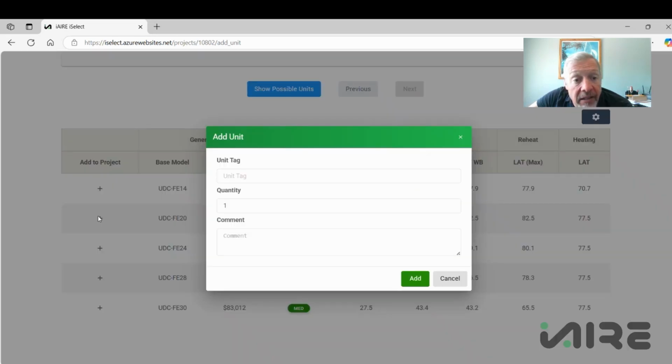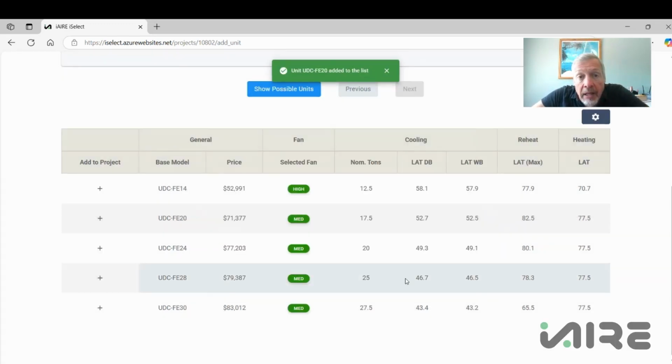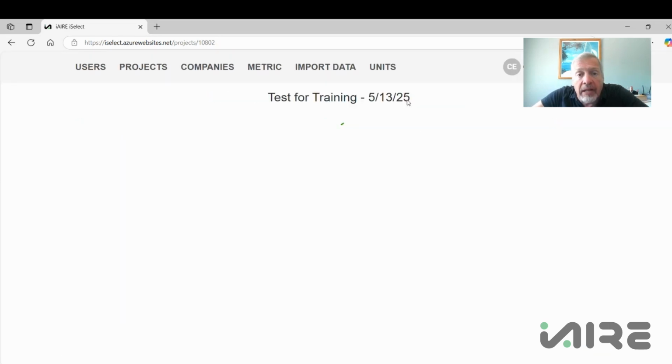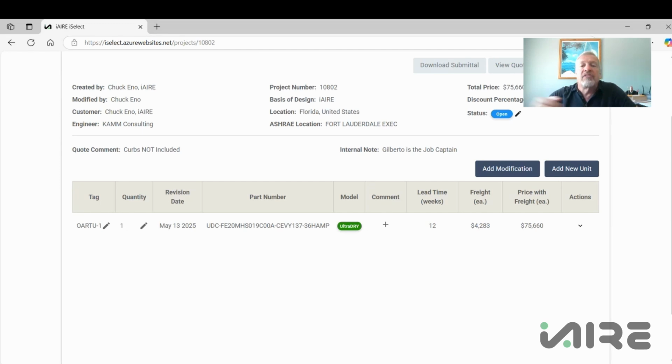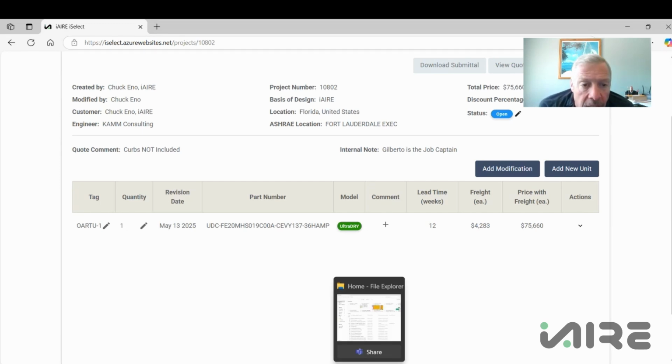So I'm going to select that FE20. I'm going to call it OARTU-1, quantity of 1, add. UDCFE20 added to the list. Okay, now I'm going to go back and look at my job. There we go. I've just selected my unit. It's going to be an ultra dry unit, FE20 based unit, medium static fan.